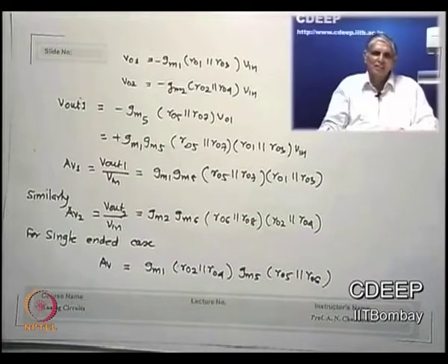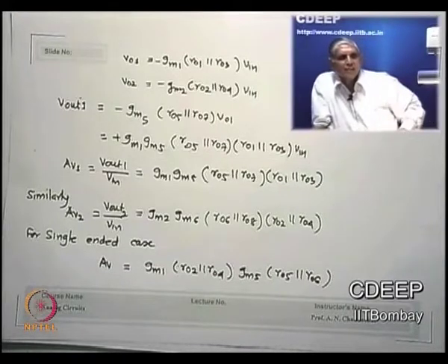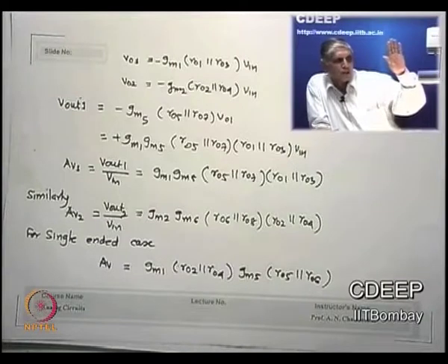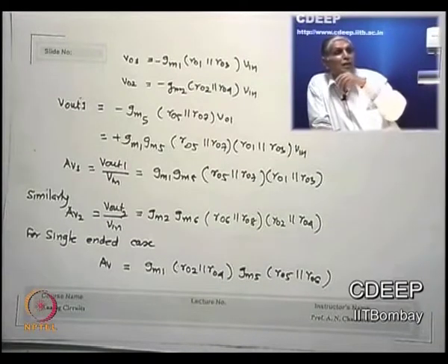And what is the advantage there? The advantage is that everything can be mirrored now from everywhere, we do not have to put any current sources directly, is that correct? Because mirrors are easier to create. Once you create a mirror source, current source, you can always mirror it to any number of places.